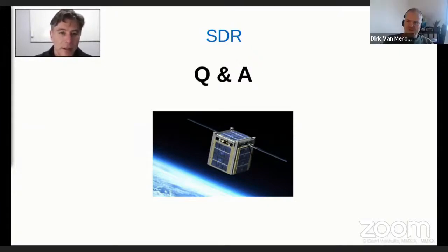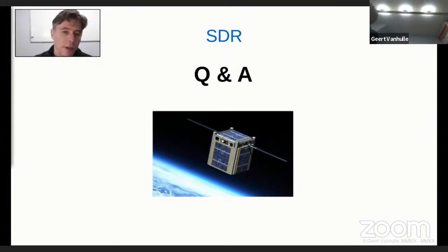So the RF stage, especially when we go to the higher orbit satellites, this is really a very conservative market, because of course, as you go further away from Earth, you need a high power output. What you see is that they typically still use the traveling wave tube amplifiers. You have the circulators, all the pipe plumber type of RF stuff, and it's quite conservative in that stage.